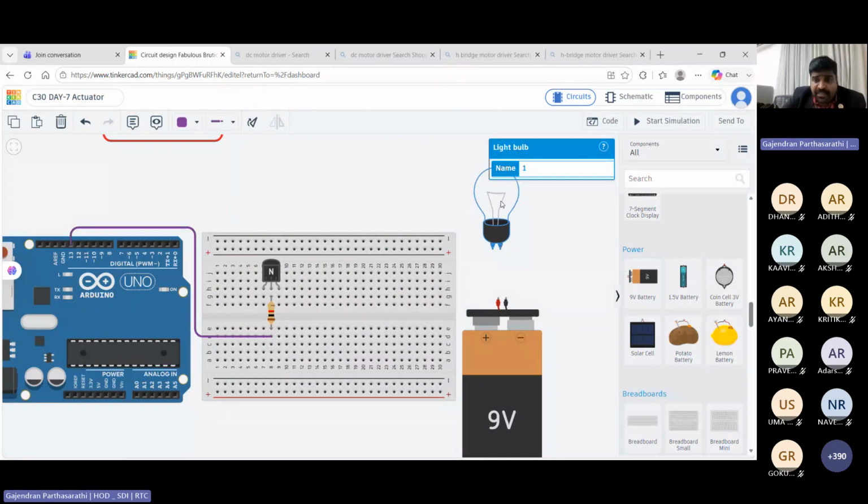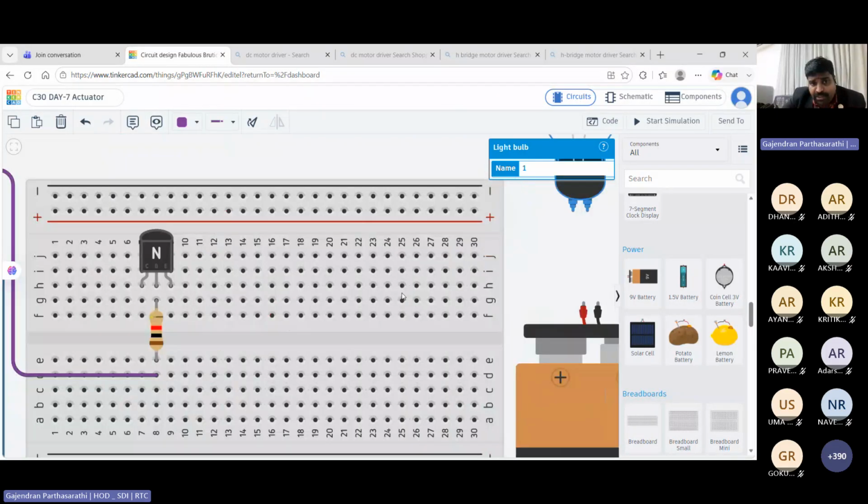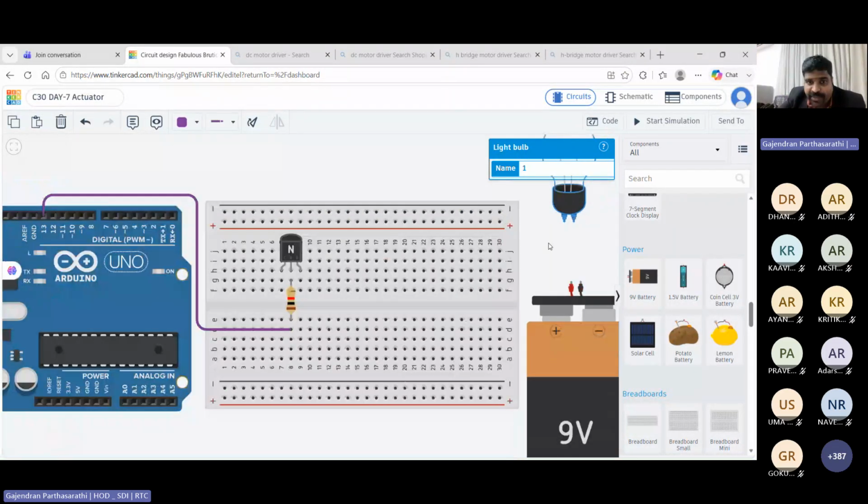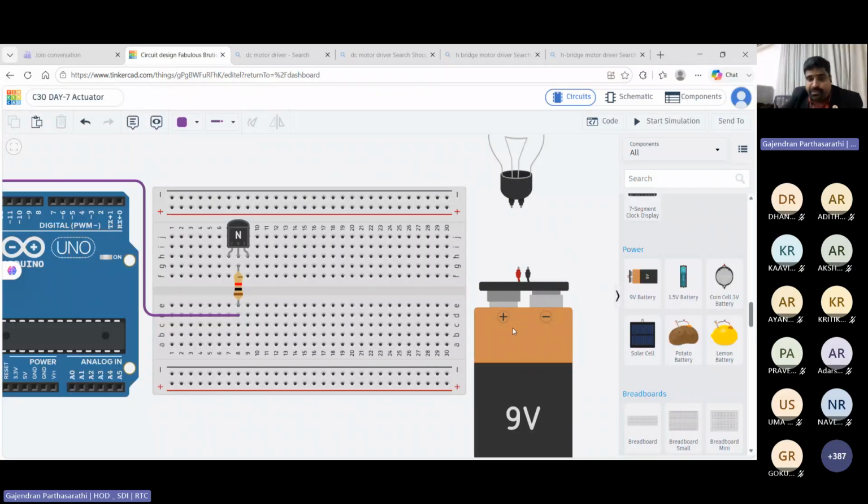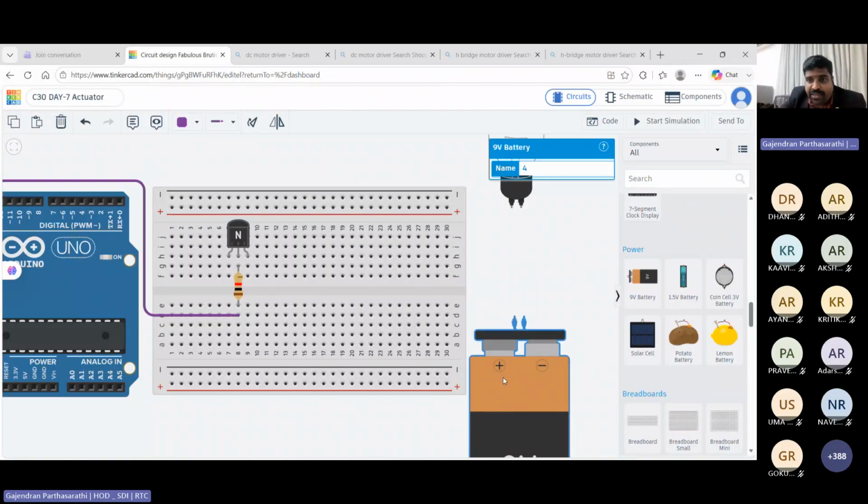see this breadboard also has a current limit. You can't drive more current with this. The green color lines indicate the conducting plates in the breadboard. If you make more current flow through this, the breadboard will heat up and melt. To avoid that, we are going to make this power circuit.